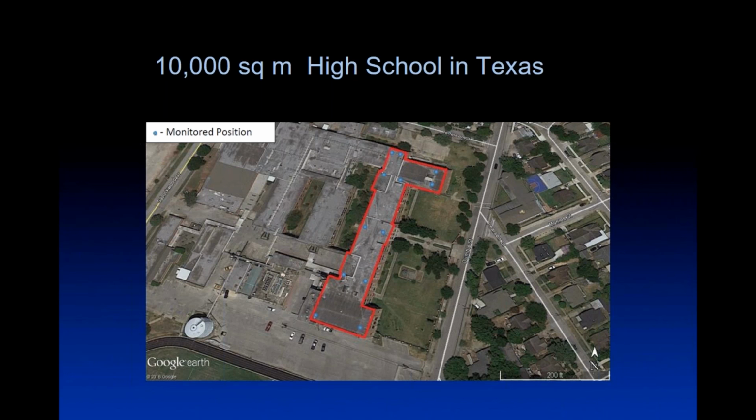Additionally, if you are worried about how you deal with a structure after an earthquake, you haven't got to wait for another earthquake to come along. You've got this baseline taken at low amplitude. The earthquake comes along, the building changes. You have a look at it again, either sequentially, so you take another set of measurements, or if you're continuous monitoring, you can see it immediately. But that tells you whether you're okay or not, whether there have been changes. It gives you a new risk profile under the new circumstances.